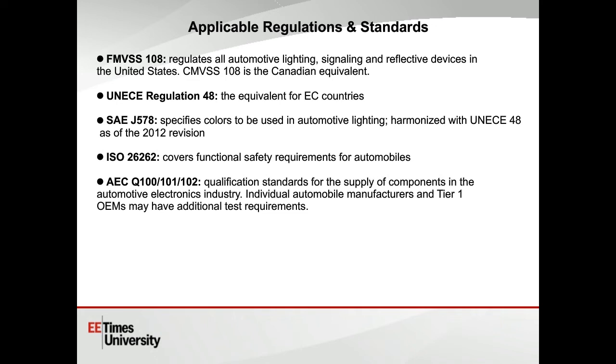It basically mandates that if anything fails, it will fail in a controlled manner, and manufacturers are now required to include a variety of fail-safe mechanisms, even down to within an IC itself. So if something fails, it will degrade gracefully, as we say, and also there will be an alternate way for the driver to recover from some failure event.